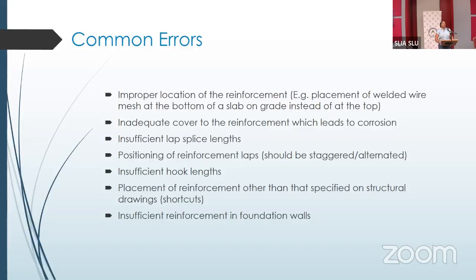Like there was a building that I went to see personally that I was interested in, a partially built reinforced concrete structure, 2 stories. And when I went to inspect it, you can imagine if I wasn't educated in the field, I would have probably just gone with it and said, hey, here's your money, give me the building. But then you have reinforcement, the main bars sticking out of some of the columns. You have reinforcement protruding so that they can later on come and build the stairs. And I'm seeing all T10s.